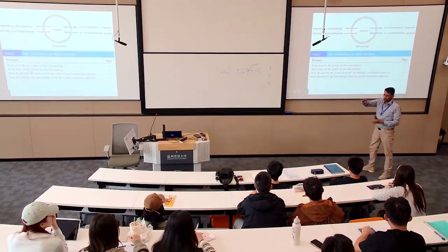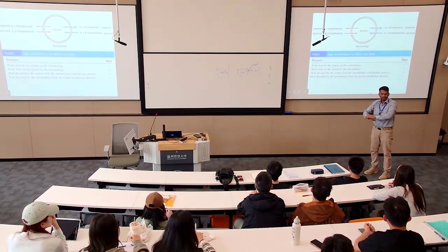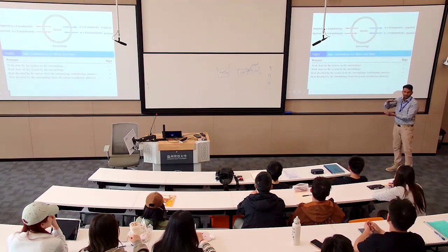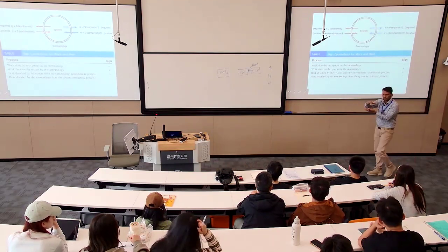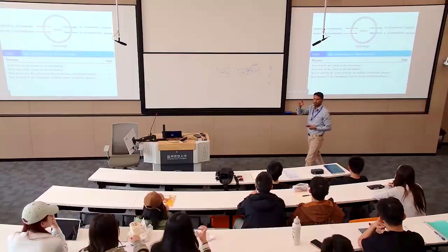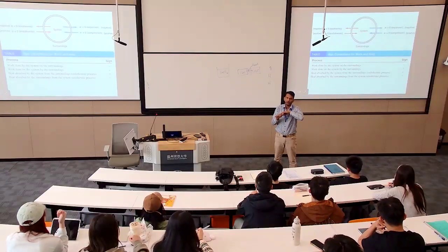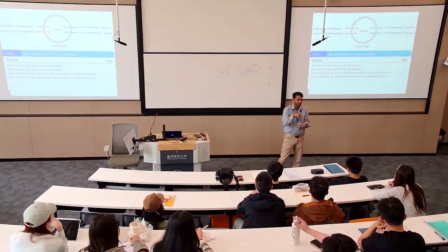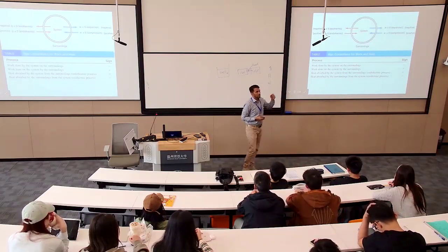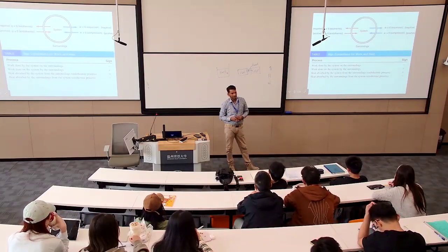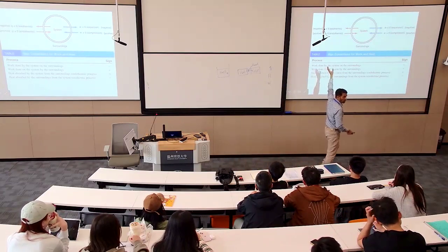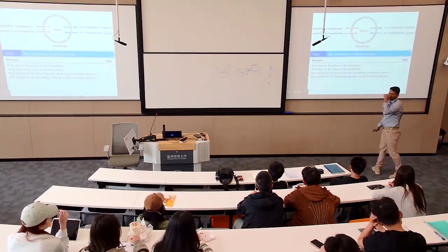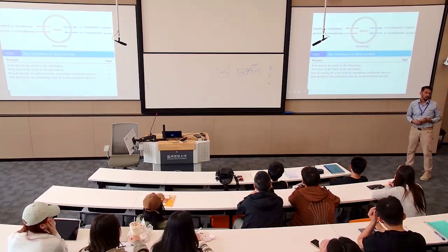If I do work on the system, I press the piston of the engine, so my work is on the system. When I work on the system, energy increases because my work is converted to energy. So if work is done by the surrounding on the system, its sign is positive.